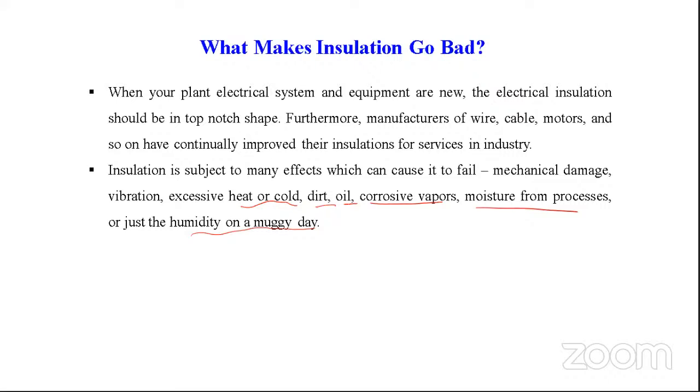So in that case, better if you measure the insulation resistance at a periodic or regular interval, and compare the readings of different measurements. If it is showing constantly a particular value, it means the insulator quality is not degraded with time.